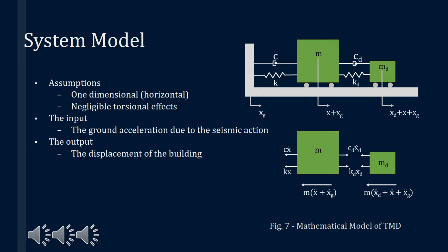We only looked into the system response of the peak maximum acceleration of the El Centro earthquake. The peak maximum acceleration is equal to the maximum ground acceleration that occurred during the earthquake shaking at that specific location. In this case, the maximum ground acceleration during the El Centro earthquake was 0.3495 meters per second squared. We analyzed the response of our system based on the worst case scenario that this maximum ground acceleration occurs instantly as soon as the earthquake waves reach the structure's location.